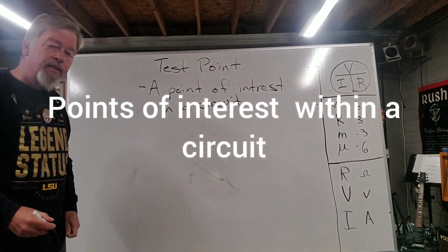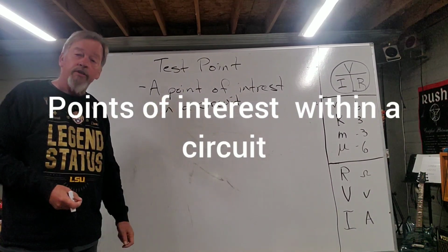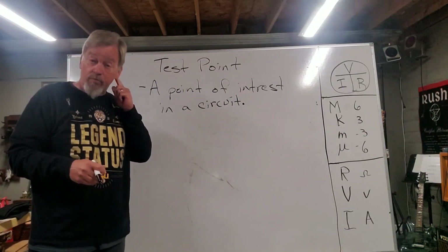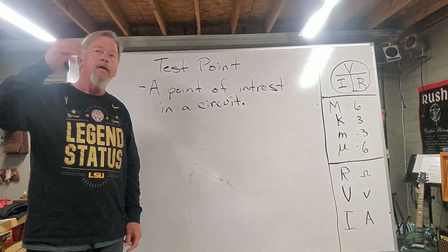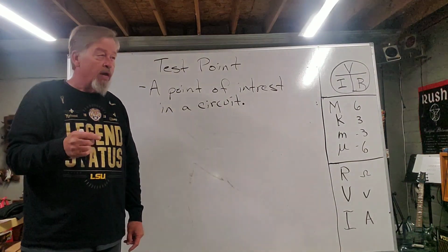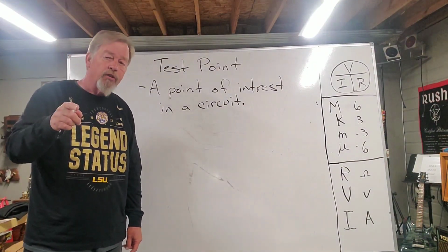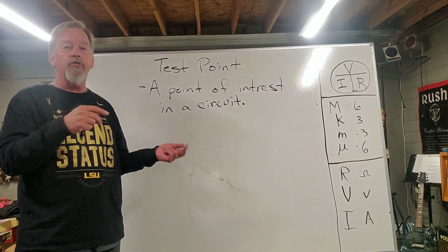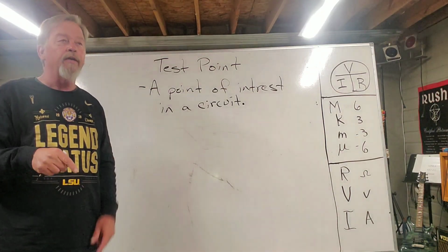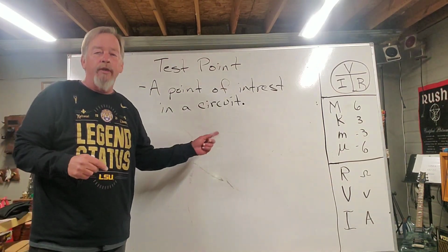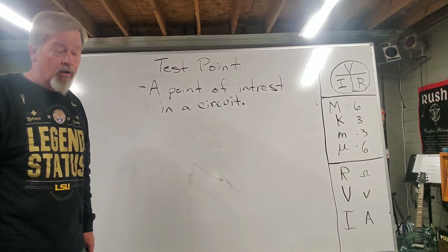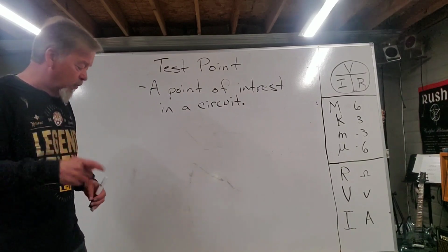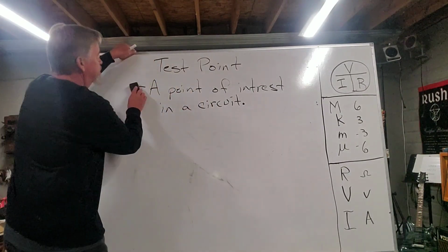So test points can be simply defined as points of interest inside the circuit itself. A lot of times in procedure, especially troubleshooting procedure, they'll have step by step. And what they'll do is they'll say, check the voltage at test point 1, check the voltage at test point 2. So these are just points within the circuit that we're interested in, or documentation determines we're interested in. Okay, so one thing you need to know about test points